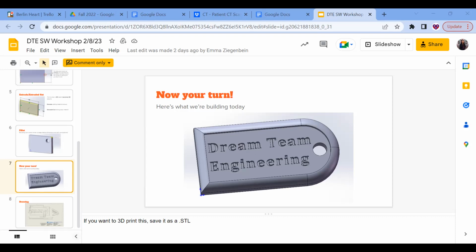So we're going to draw another line from the bottom here. And you want to, again, make sure you're on the origin. And you can see there's a little relation there. And then another horizontal line. And the little dotted lines, that's SolidWorks guessing that we want the lines to be parallel and equal. So you can see the two relations and then the dotted line. That's where we want it to be, so we're going to let it do that for us. And now press escape. So you should have an open rectangle.